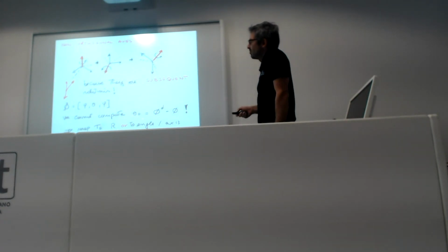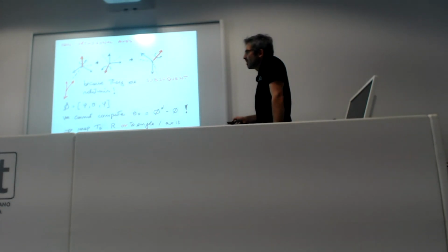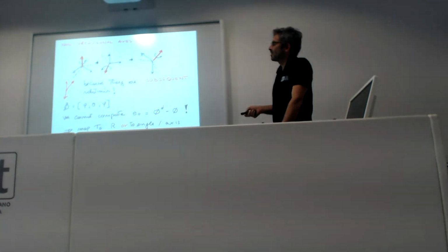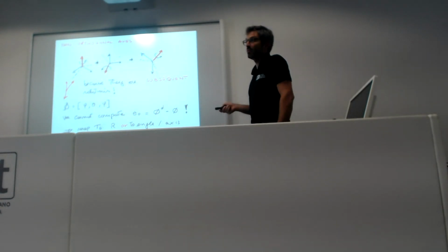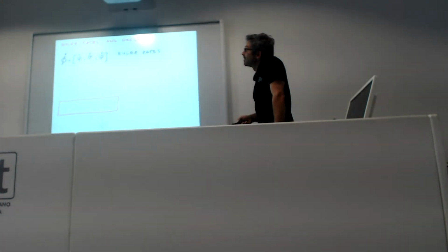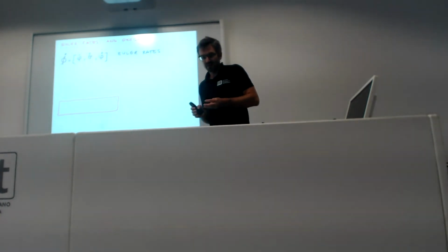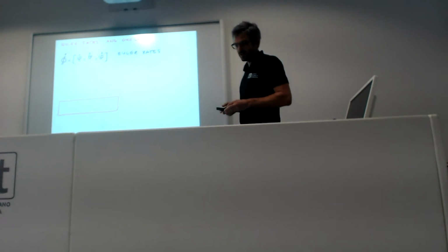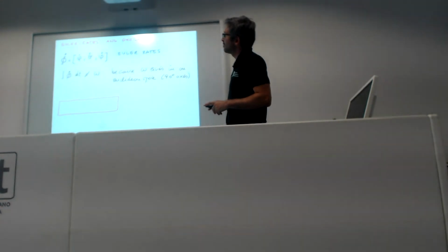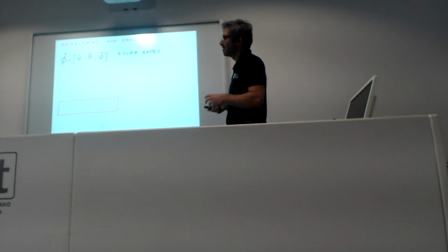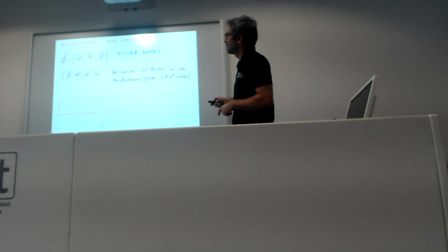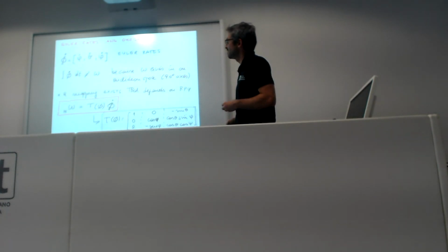So that's why you need to map these Euler angles to a rotation matrix or to angle axis, because angle axis is defined in a Euclidean space, and then you can map it into a moment and do the control. The fact that these Euler angles are not in a Euclidean frame means that their derivative is also not in that space, the axes are not perpendicular, and therefore you cannot get omega by integrating the Euler rate, because omega lives in a Euclidean space.